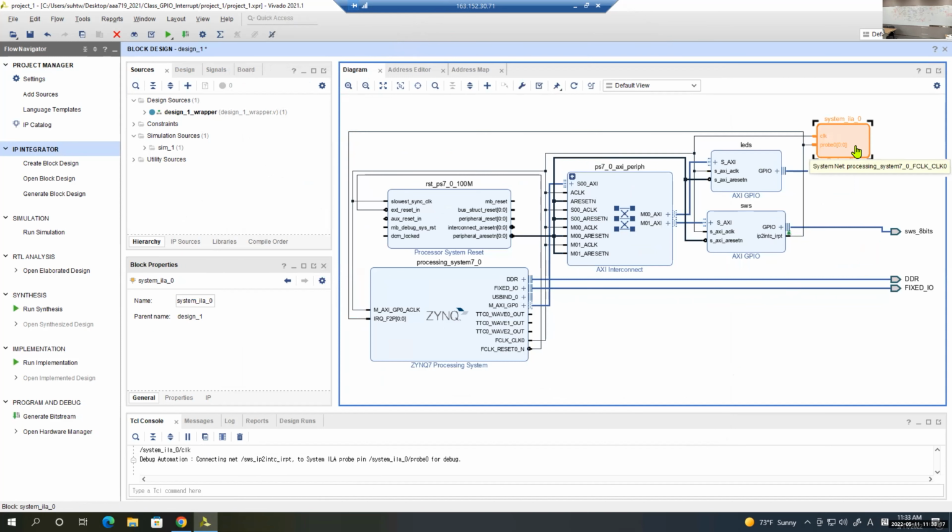So you know the hardware mechanism is very similar. Every clock cycle, the ILA is sampling. We have the integrated logic analyzer. You have the clock input and the interrupt wire connected. The clock is running very fast, and the interrupt is generated.